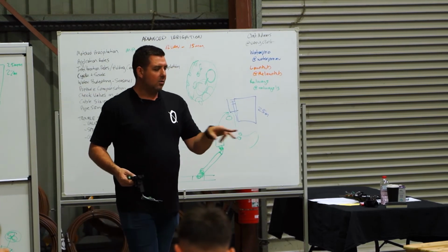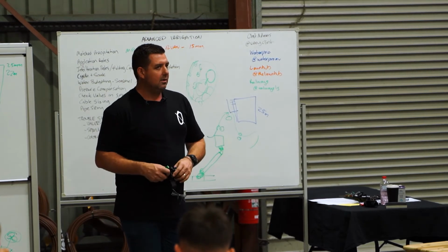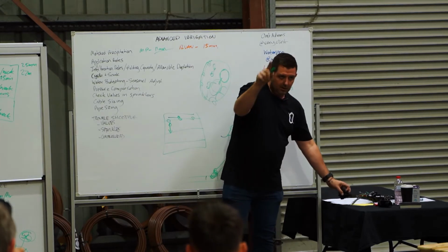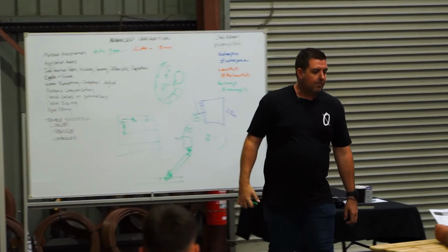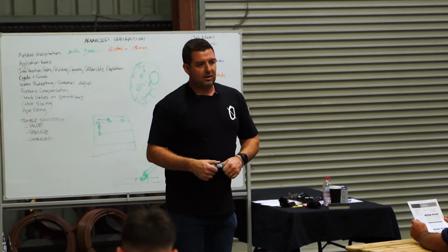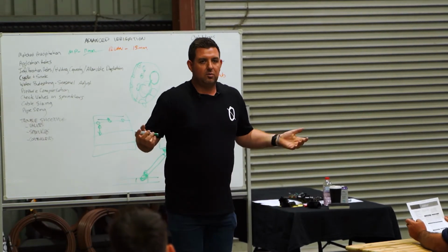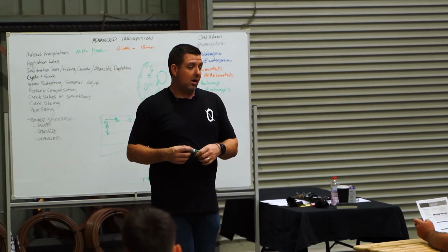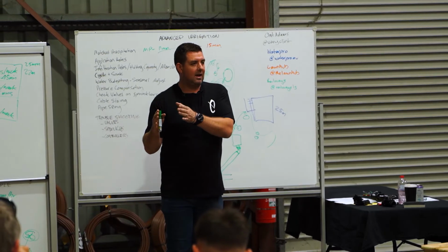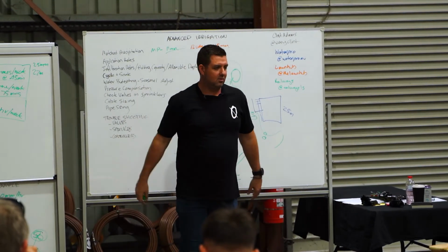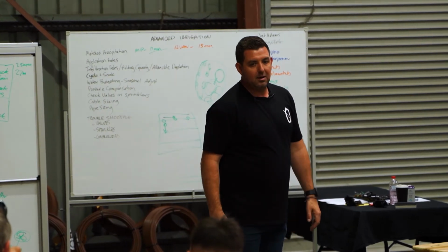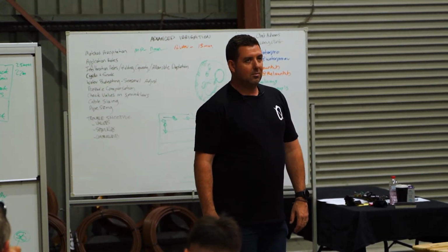It's interesting to note 1 mil is really rarely used. Like, we design 1 mil a fair bit because it fits so many. If you ever look at the 1 mil by 1 mil, it goes so far. But it's just been, again, one of those things that irrigation design firms for the last 20 or 30 years have just used 1.5. I would theorize that it's because it's easy and it means they don't have to change a block template in their CAD software, so they just spit out the same thing and just hope that no one notices. The good thing is irrigation shops sell more cable and make more money, but it's over-engineered in some cases.